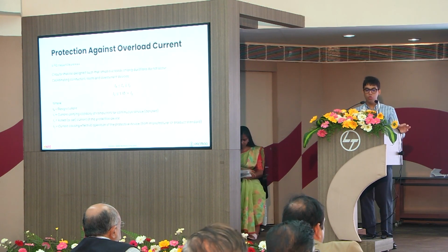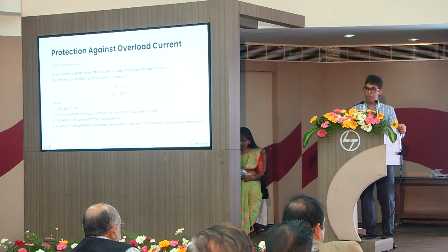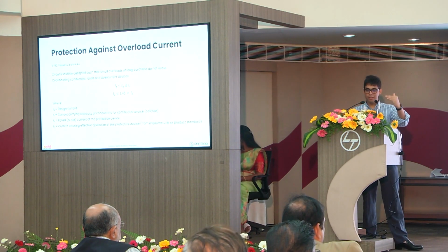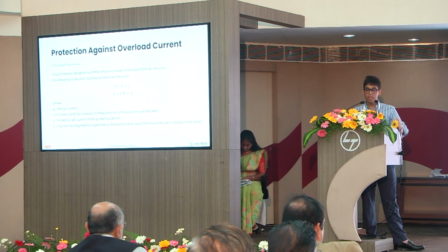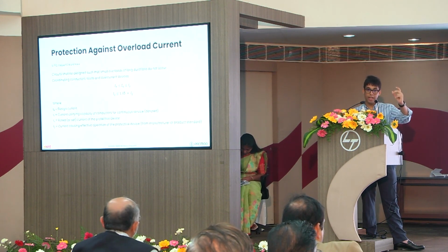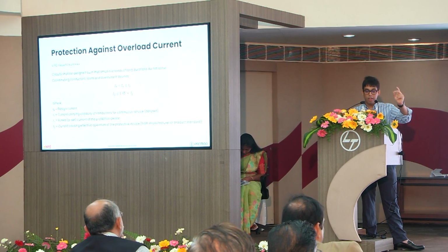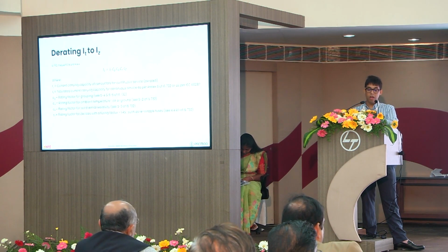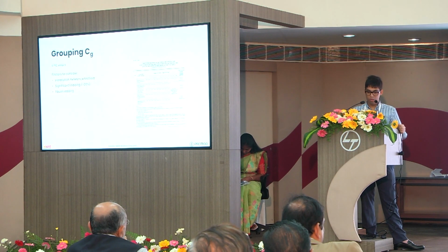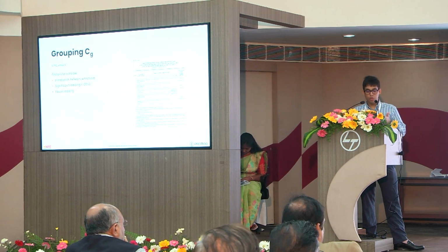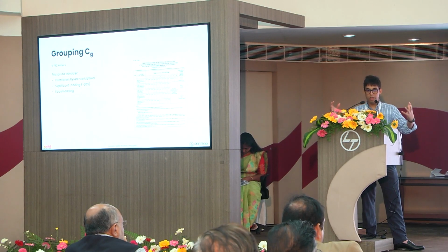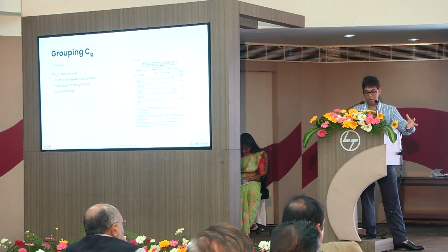So if I2 has to be lesser than or equal to 1.45 times IN, any circuit breaker or overcurrent protection device, mainly fuses where this issue happens, that has a fusing factor greater than 1.45, we need to then apply a correction factor. How, we'll get into.